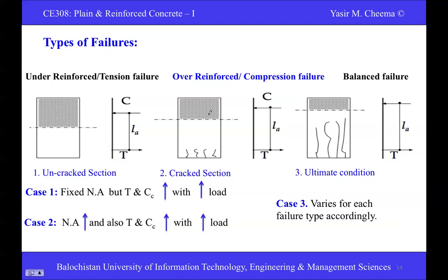You put some loading and whatever the moments, you have heavy amount of tension produced over there. Steel will not crack, steel will not fail. You put more steel over there. It's over reinforced. It can tolerate, it can accommodate more tension. But your concrete cannot have so much efficiency that it can tolerate so much load.